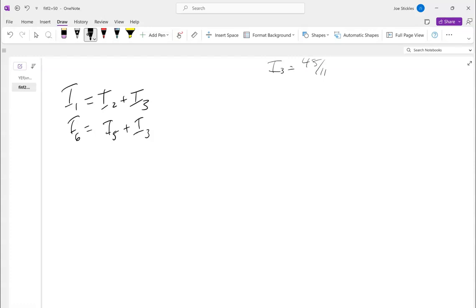The I1's coming in, and then I2 and I4 are going out. Yep. So I1 equals I2 plus I4. Finally, the one on the right here. I4 plus I5. Good. And again, those are just equating outs and ins, right? Just like what we did with the flow problems of the pipes. There's nothing different about that.